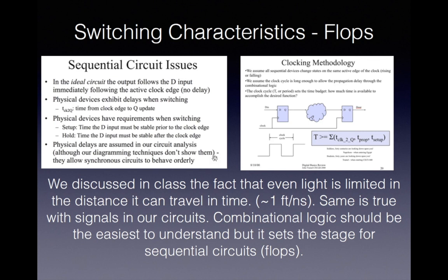So when I look at a representation or an abstraction of a typical digital circuit in the right-hand window, I can see the typical circuit starts with a flop, which is switched on the active edge of the clock. It passes through some combinational cloud, and then it has to arrive at the input of the next flop.